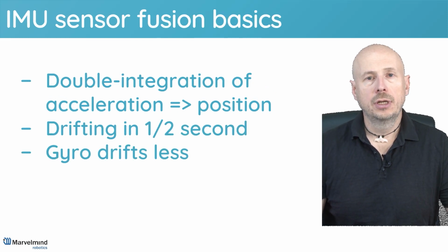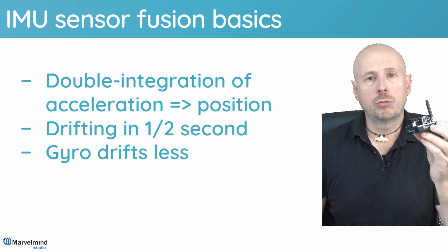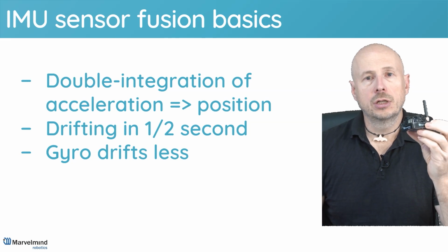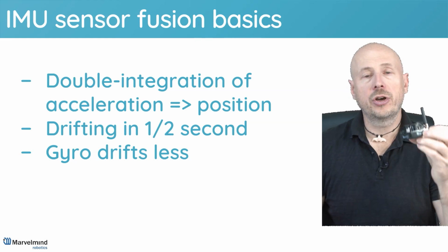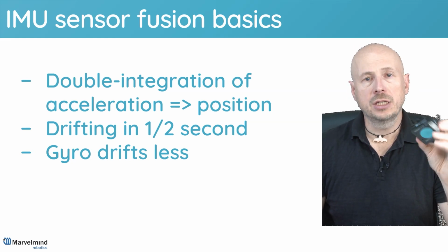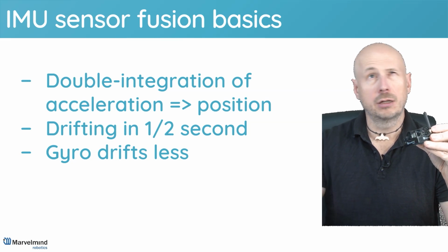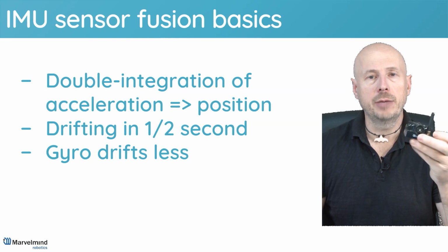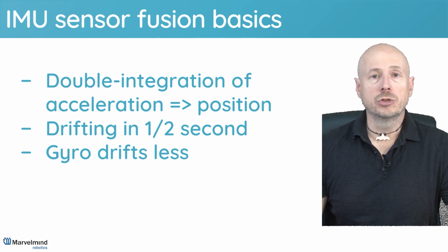So what's the difficulty? The difficulty is in the double integration of acceleration. The accelerometer data, if it was in, let's say, zero gravity, would be very simple, because we basically integrate it, and that's good. Even the basic MEMS, so micro-electromechanical systems, MEMS IMUs that are typical in your phones or in our beacons, are good enough for this because they have low drift, etc.